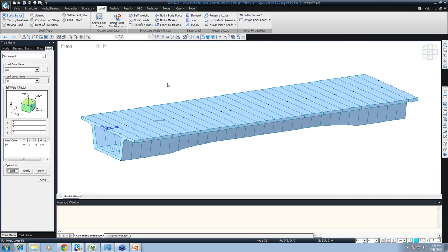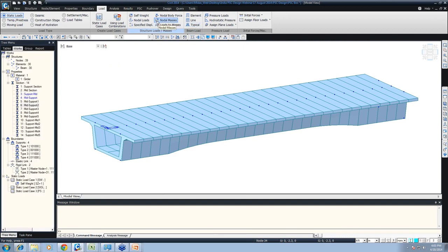So -1, what it will do, it will automatically, since the weight density that we have given already in the material properties, we have defined some weight density, that is WC. So it will automatically take -1 into WC. So whatever weight that has been given will be considered. Weight density that has been given, it will calculate the self weight according to that.